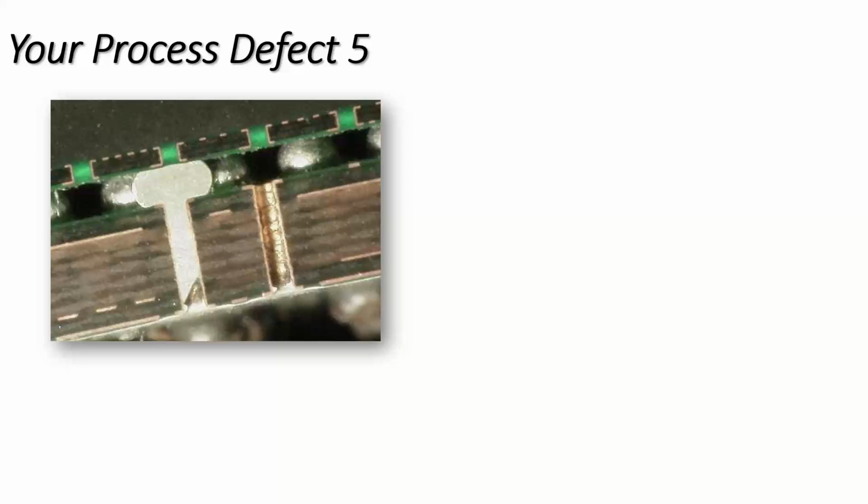It's a nice image. I didn't do this microsection, I have to add. Now, in my opinion, and I think most designers', it is bad practice to have open vias directly underneath BGAs. That's the first thing. But what's actually happened here, if I remember correctly, is a 0.3 via, but the company concerned had managed to get solder to penetrate up to the top side.